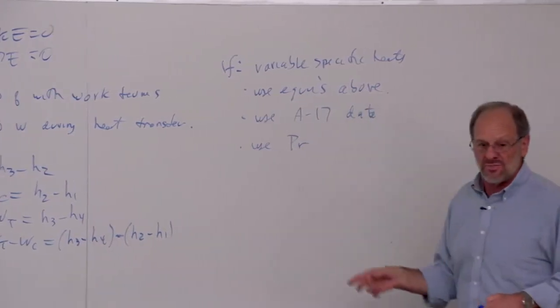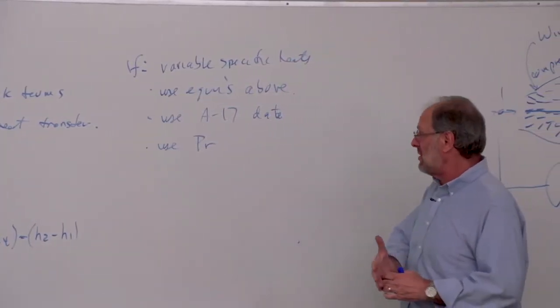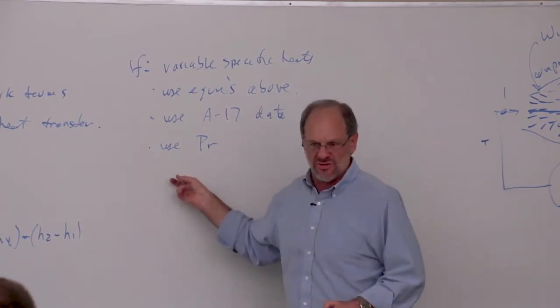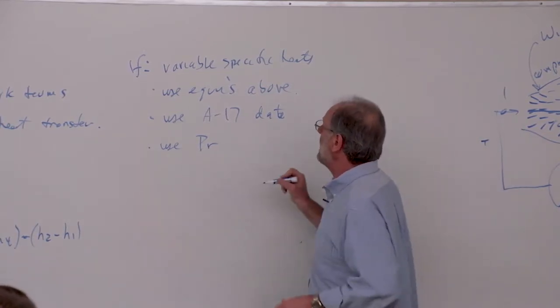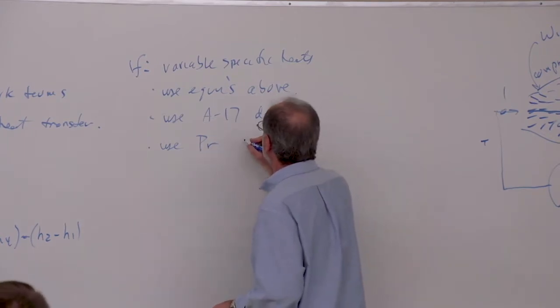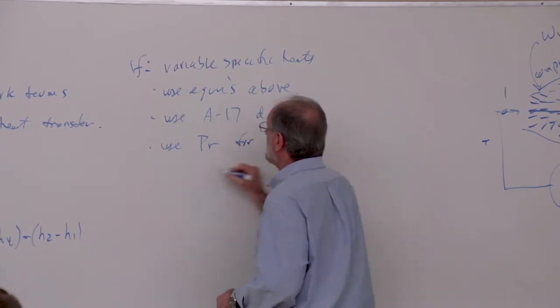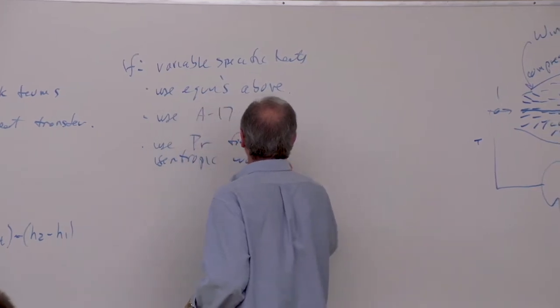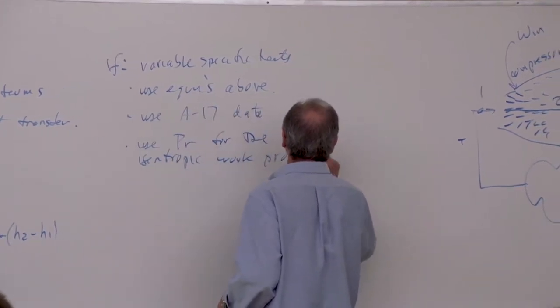Nonetheless, it's called relative pressure because the pressure ratio equals the ratio of relative pressures, so we just use the word relative pressures, but it's not a pressure term. Anyway, we're going to use relative pressures for the isentropic work processes.